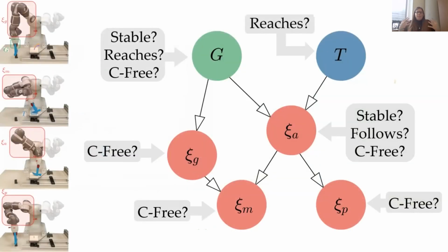Okay. So returning back to this constraint graph, it is nice in that it captures our entire problem. But as a reminder, we are doing this in the context that we were given a fixed sequence of actions, that we told the robot, do this, do this, do this. From that, we identified our variables and our constraints, and by hand, we walked through how to generate this constraint graph. But this is limited, and this is the limitation that I care the most about, because the robot has no flexibility in how it completes the task. We've prescribed that you must do it this way, and therefore it's not going to be able to generalize to any different kinds of environments.